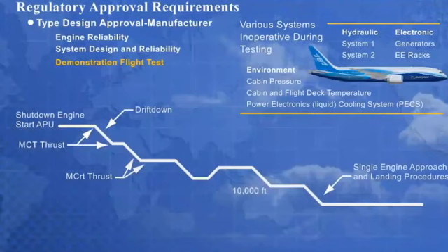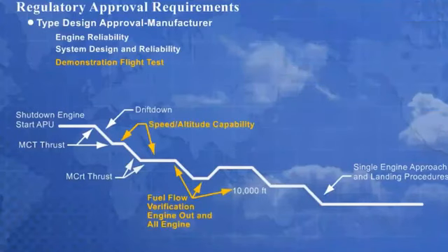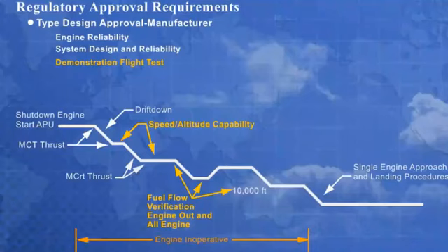The flight test program verifies the airplane's flying qualities and the flight crew workload with various systems inoperative. Flight testing is also used to verify the airplane's ETOPS-related performance. Engine inoperative segments in excess of 330 minutes are typically performed on modern long-range ETOPS airplanes to demonstrate unrestricted routing capability.